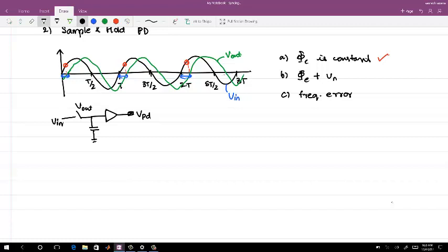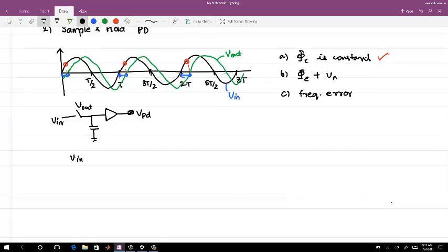Okay. So if my signal V in equals A in sine of omega t, and I am sampling with V out, then sampling it with V out will give you A in sine of omega n times t out plus delta t, right? T out is the time period of the sampling clock waveform. Delta t is the shift from the instant t equals 0.